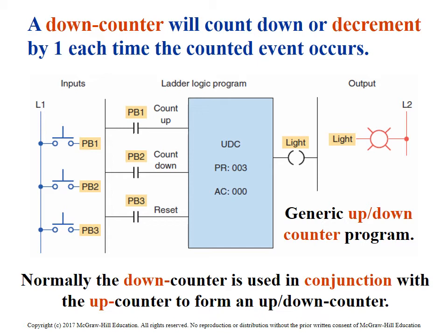What does that mean for us? That means that when we're counting down, say we're counting down from 10, we get down to, say, 5, and someone triggers a reset for that counter. Intuitively, you're probably thinking, oh, that should set back to 10, so when it starts counting down again, it starts from 10. No, when you hit that reset, it puts a 0 in there. So the next value you trigger into that countdown counter is going to be a -1. So keep that in mind. There's a question or so on the test regarding that as well.